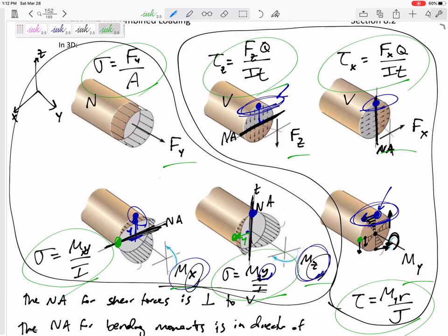How about this green dot? This green dot, I would combine this down shear stress with this down shear stress right here. This one I would not combine. It's 0, but also even if we were looking somewhere over here, don't combine a left-right shear stress with an up-down shear stress. Okay? But let's step back and look back.